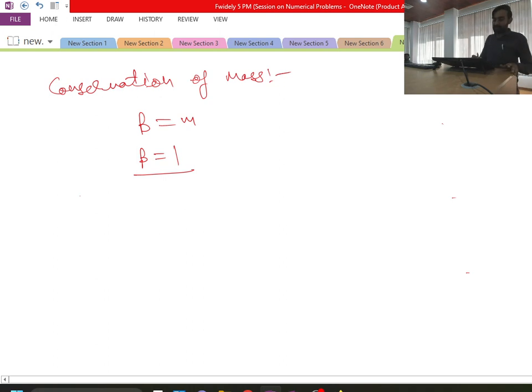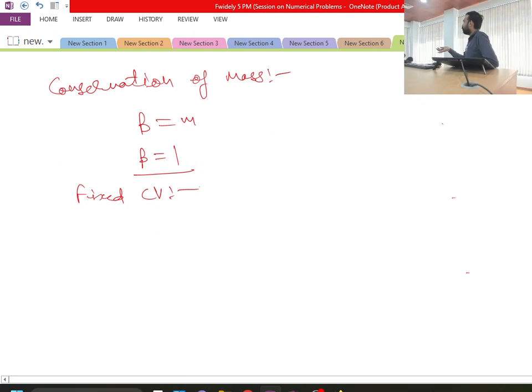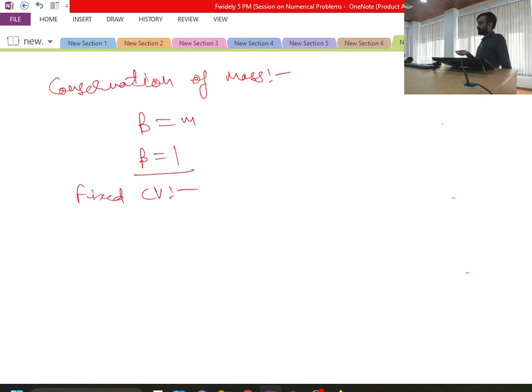Apply now the Reynolds transport theorem for a fixed control volume. Majorly we will be deriving all the equations for a fixed control volume, because that is what will be there in the majority of cases of this course. For some cases we will have a moving control volume. These we will refer to case by case.